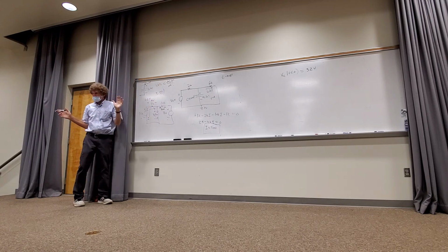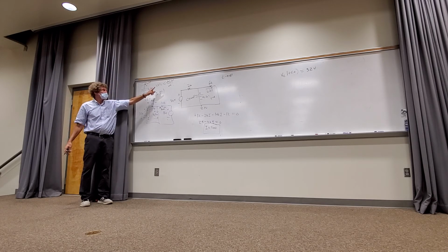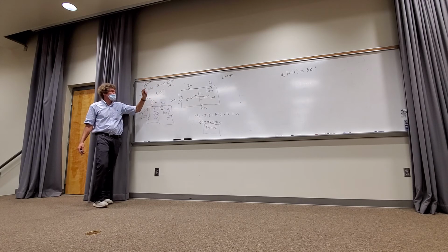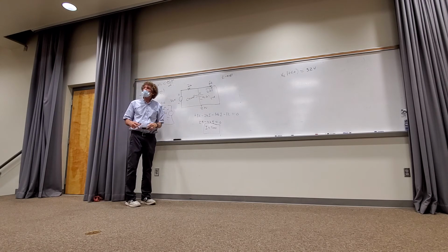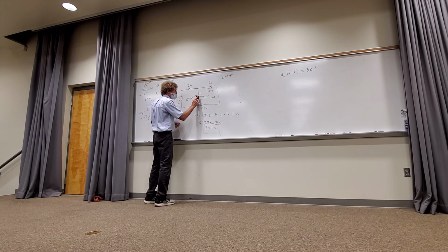Now, listen. If there is nothing changing with time, do you see the current is 0? Right? As t goes to infinity, everything settles to a steady state value of V. Y'all follow me in that class? Nothing is changing with time. It means the current's 0. If the current is 0, it looks like an open circuit. That's my real point with these capacitors. When nothing's changing with time, for t less than 0, then on forever, it looks like an open circuit. As t goes to infinity, it looks like an open circuit too.